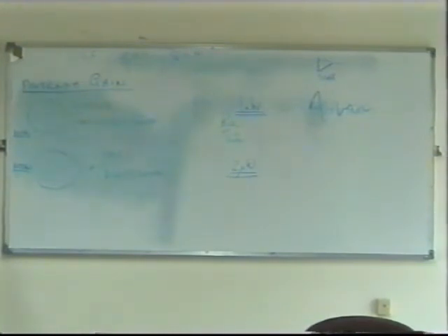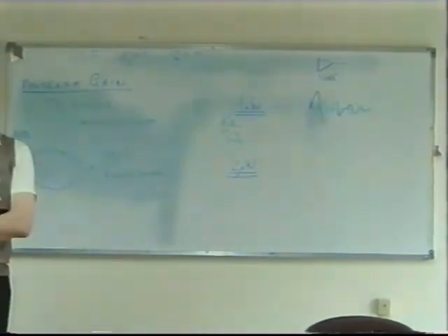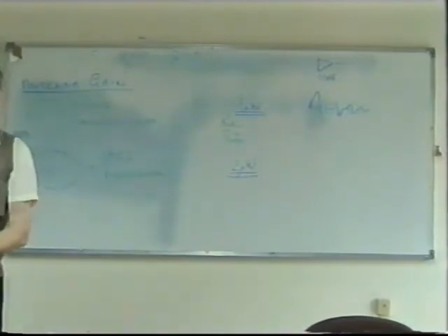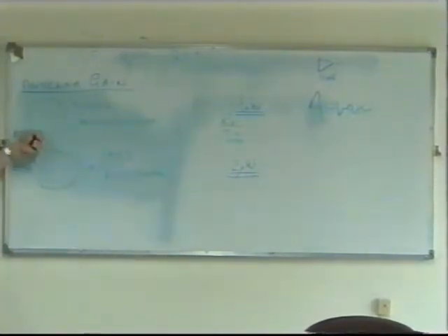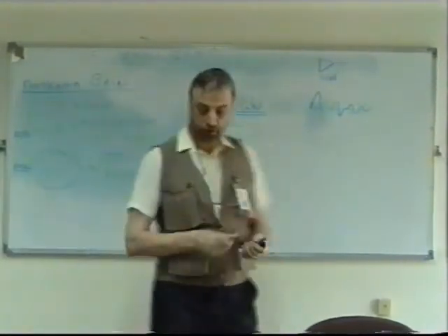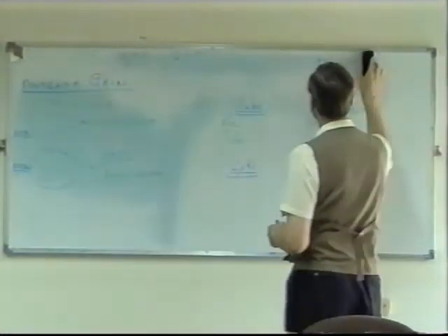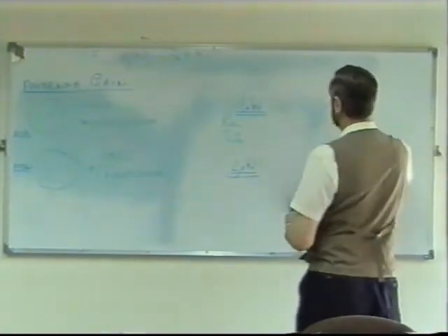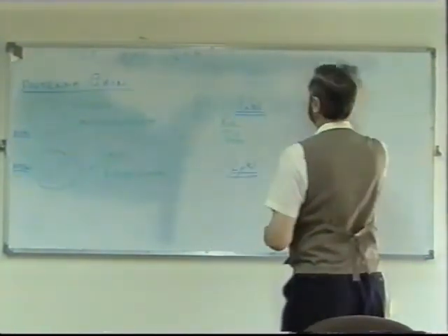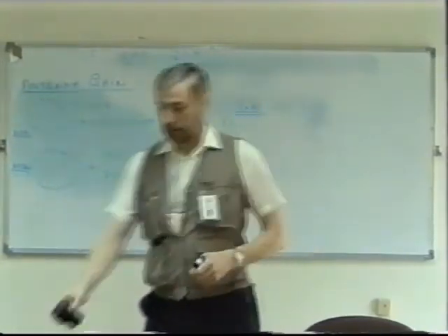We call this antenna gain. It's not actually amplifying the signal. What it's doing is not wasting it. That's basically what it's doing. But it appears as though it's the same thing as increasing the power of your transmitter compared to an omnidirectional antenna. Yes, technically, I'll put the definition down here. It's the signal strength at the receiver. Let me put it down, then you can see it clearly. If you increase that power, you increase the gain, the antenna gain.